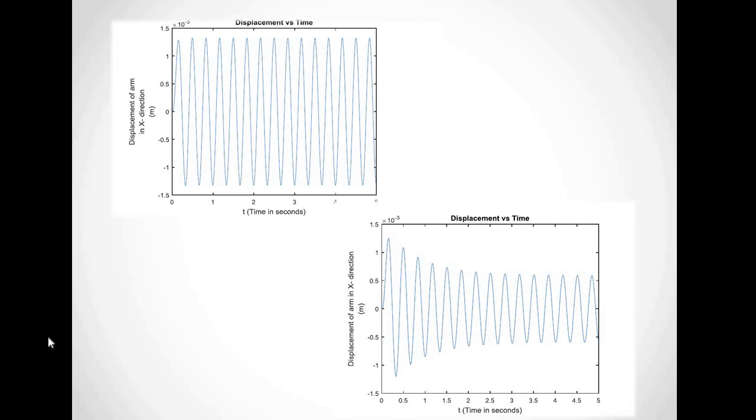The results were carried out in a time and frequency domain for a period of 10 seconds at 3 Hz frequency. The result of the hand without the vibration absorber system were in the range of minus 1.5 to 1.5, and the amplitude of harmonic displacement remained constant.